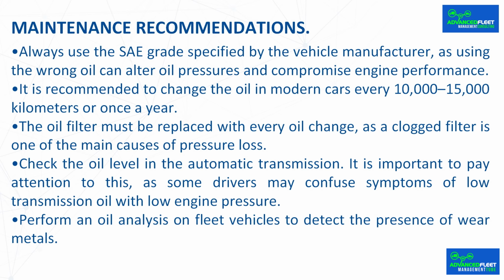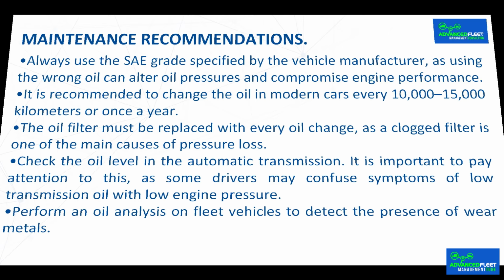Check the oil level in the automatic transmission. It is important to pay attention to this, as some drivers may confuse symptoms of low transmission oil with low engine pressure. Perform an oil analysis on fleet vehicles to detect the presence of wear metals.